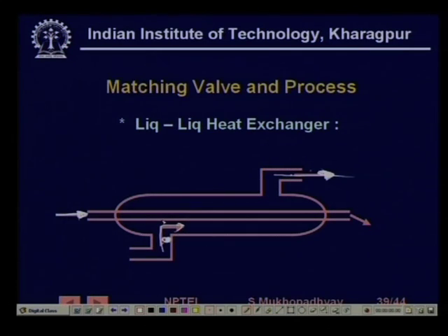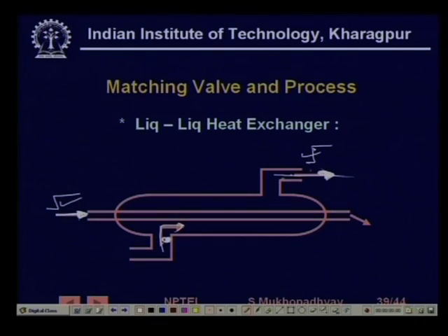Not only that, if you make a step here, the delay before the output goes up will also be higher, because the liquid is travelling slowly. So this is a situation where you have high gain and a high delay.